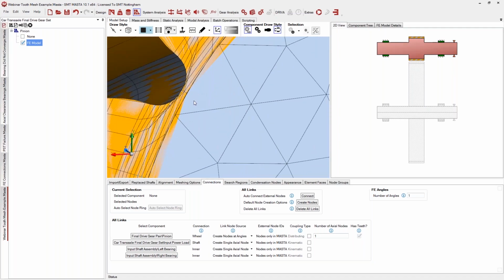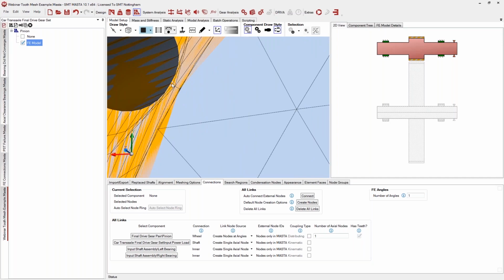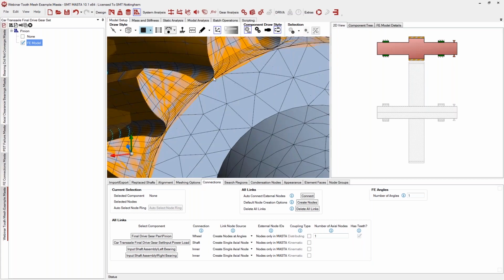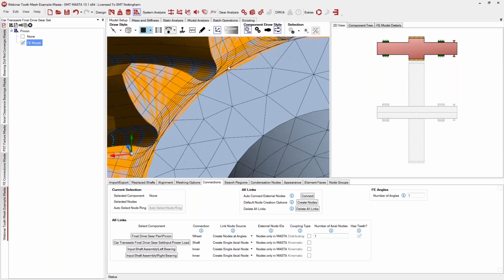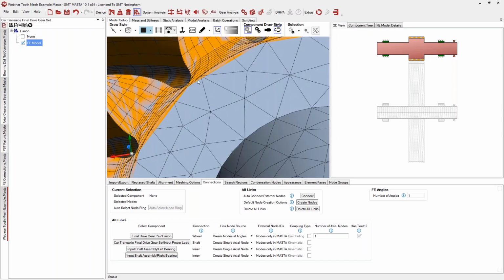or the problem that we see is caused by this FE that's generated for the gear teeth not having enough space to extend because of the gear blank mesh. So you see that the gear blank mesh is very close to the root diameter, and this now doesn't give an opportunity for the tooth mesh to be formed and also to be stitched with an MPC connection to the gear blank.